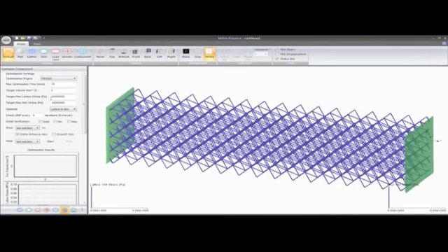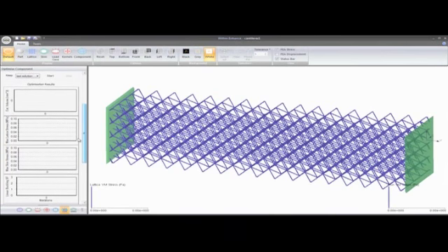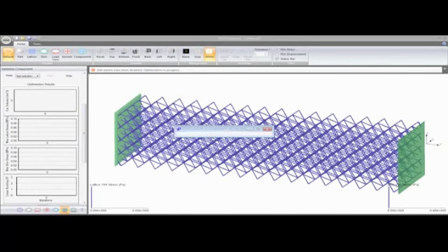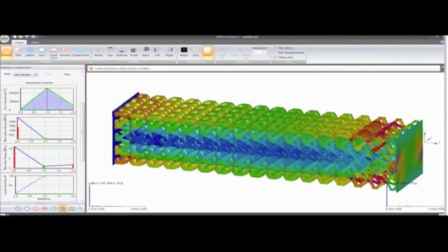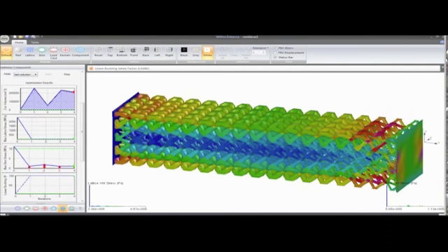So what we do with our software, we can fill it with this complex lattice structure, which we can now build because of additive manufacturing. But what we want to do is ensure that when we build this, the part works. So we need to do what is known as finite element analysis, or essentially simulate the part to ensure that it works. So what we do with the software here is we've actually simulated the loading conditions, or how the part is stressed and loaded under normal day-to-day use. And we ensure that we then create this very organic, as you can see, slowly optimizing internal structure here, which is now replacing the solid. These colors are representing variations in stresses. So in some places, the part is actually highly stressed. There's a lot of pressure there.